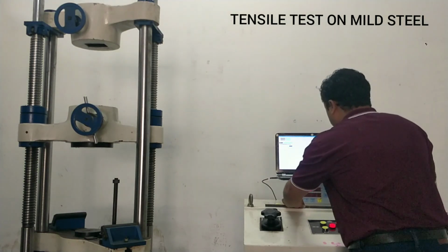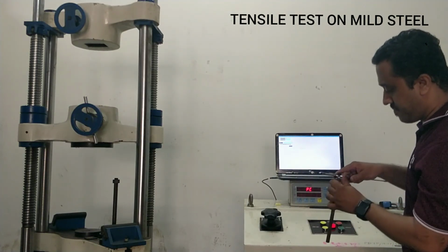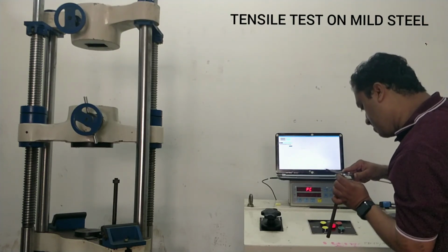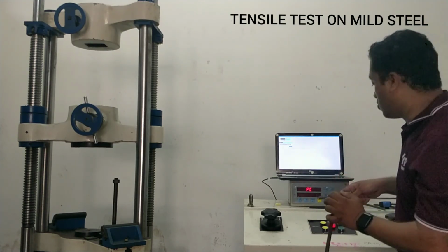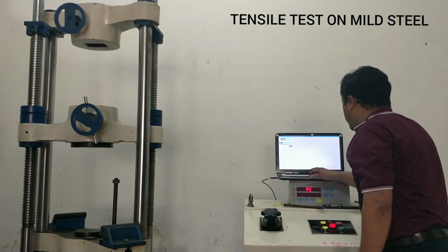We have to measure the final diameter using the vernier caliper. Use the vernier caliper. It is around 8.9 mm. So we put it here, final diameter as 8.9 mm.